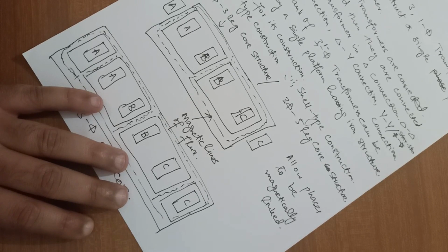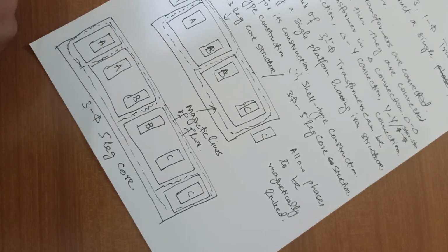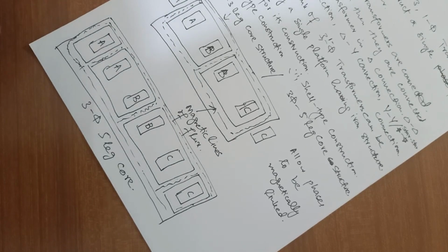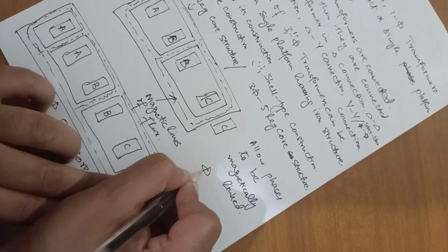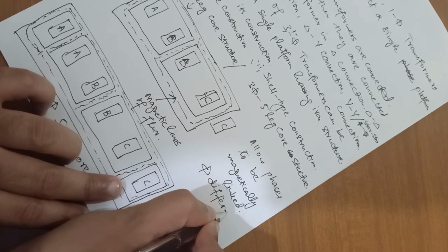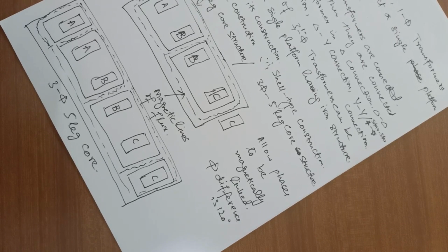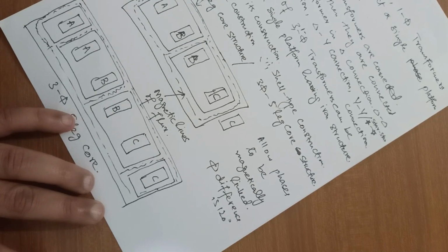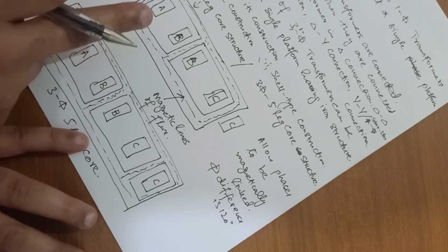So the flux across each limb uses the other two limbs for its return path, with 3 magnetic fluxes in the core generated by the line voltages. And as you know, in this case there are 3 phases, so the difference between each phase is 120 degree, right? Phase difference is 120 degree. You already know this, as I have told you in the previous lecture. So the flux in the core remains nearly sinusoidal, producing a sinusoidal secondary supply voltage, right? So this will be in this method.